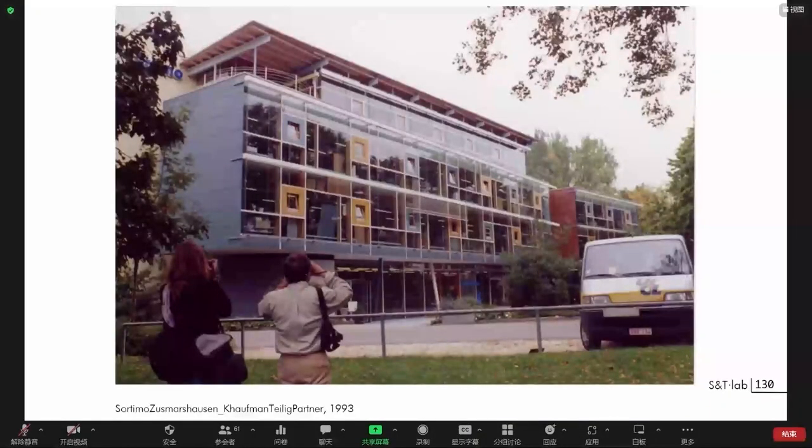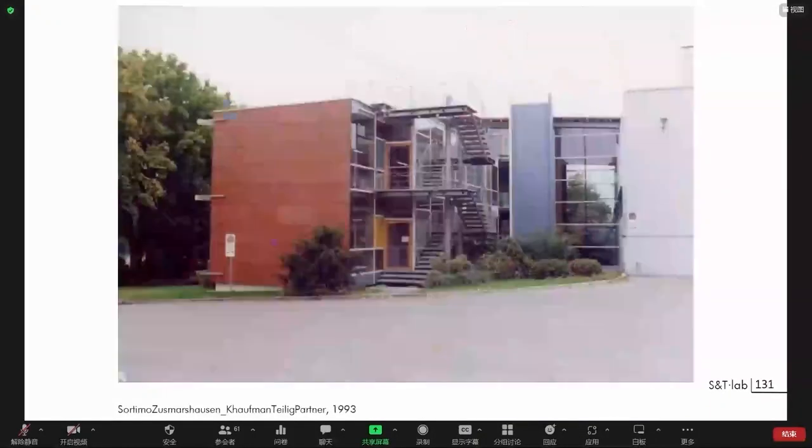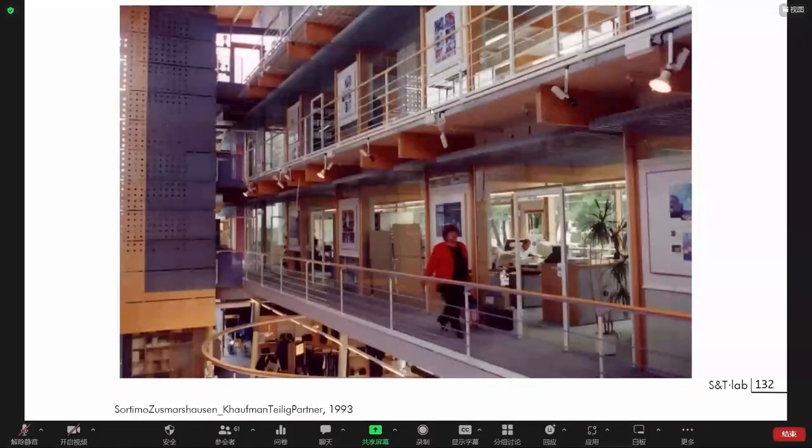Some contemporary examples in architecture, just to discuss what the strategies would be, again, finishing the systems and protecting them. Timber can be something that does not appear as timber in some examples. You can use a thin element of timber or even steel in the place where you are not able to guarantee that the timber will be long standing, for example. And you can associate the timber with a screed made of cement, for example, to raise the level of performance of floors.